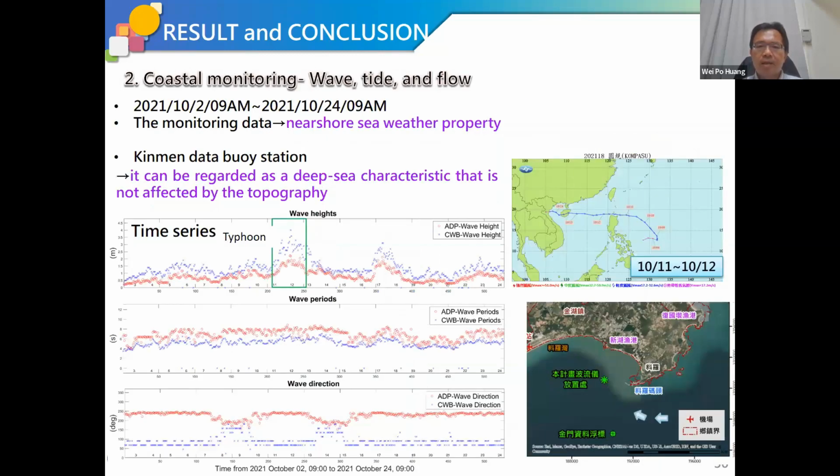Short-term measurements conducted using acoustic Doppler profiler played a crucial role in calibrating simulated parameters. These measurements were then compared with long-term deep-sea measurements to ensure accuracy and reliability. The study specifically delved into the analysis of wave refraction and diffraction, examining how the propagated waves behave in the situated area. This comprehensive assessment helps refine the simulation parameters and ensures that the simulated wave patterns align closely with the in situ measurements through both short-term and long-term measurements.